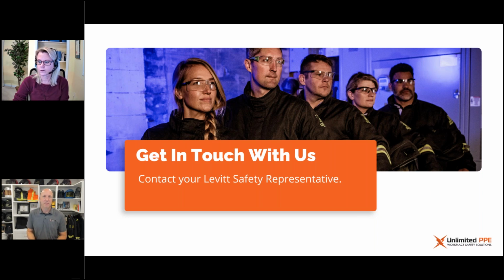Once you have achieved this electrically safe work condition, you verify it as part of that process, you verify the absence of voltage, then you no longer require arc flash PPE, unless there's some other hazard that you are also trying to protect yourself from.